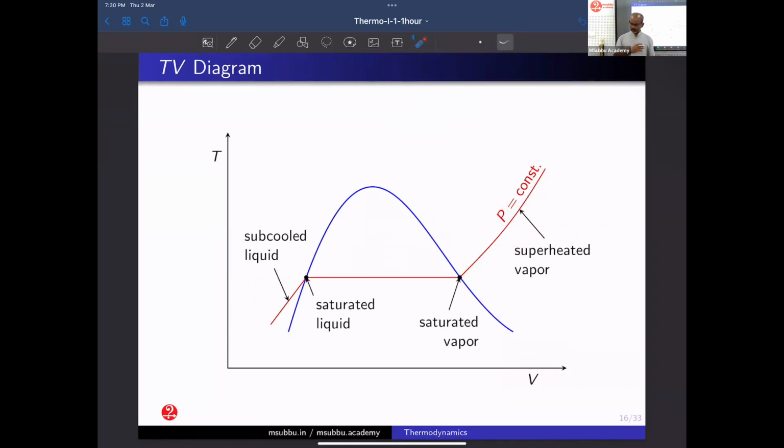And in thermodynamics, we have simply pressure, volume, temperature. These are the three important variables. And out of these, we will be mostly dealing with pressure and temperature, because these two properties can be easily measured. How do you measure? Simply put a pressure gauge or temperature gauge, or a thermometer or manometer, which give the indications of pressure and temperature. Whereas the volume of the system creates a lot of problems. For a flow system, we cannot easily measure volume. Even for a closed system, volume is again a function of temperature.